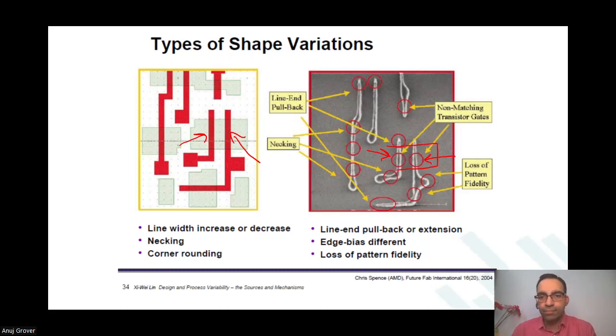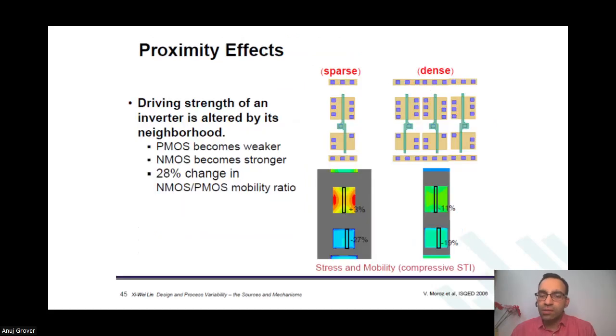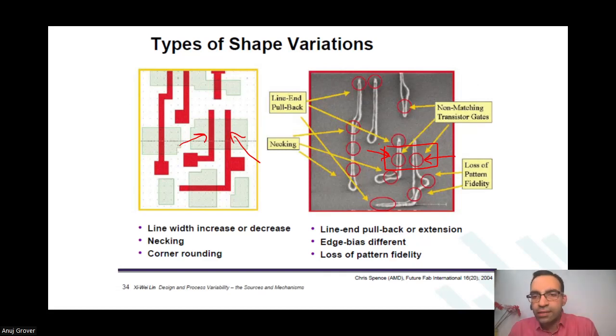And you see that the length of these two devices is different in this region. It has also been circled there. The thickness of the poly means the length of the device. Yes. So it is different. So it means these two devices, which are supposed to have the same length and same width, would now actually have different characteristics. Am I right?